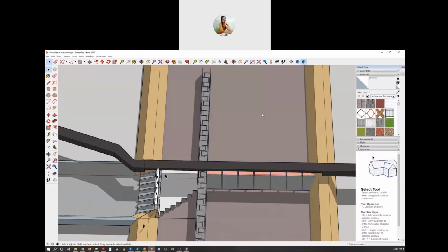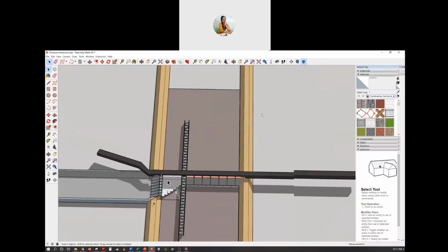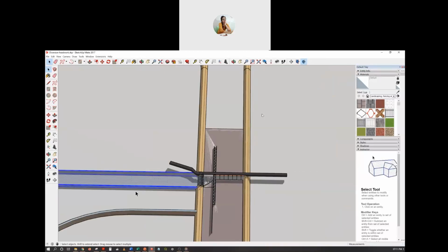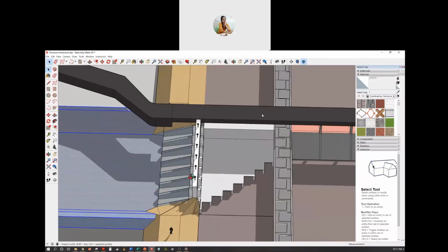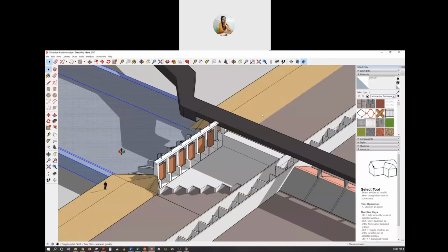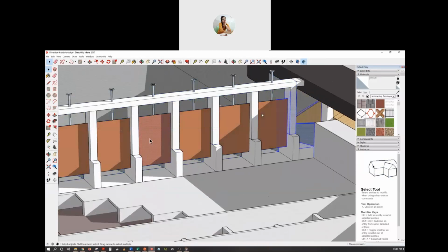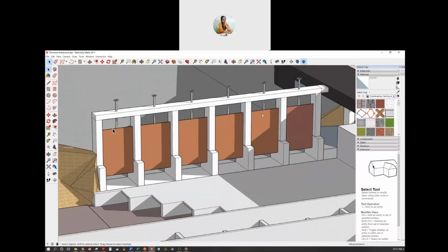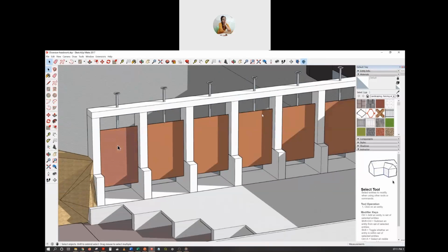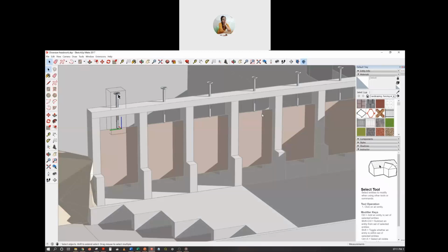Now, the off-taking canal is fed by these kind of work, which is called a head regulator. So a head regulator is provided with these kind of gates. So these are the gates. Mostly these are made of metal and they are raised or lowered based on need. So here I have only shown this kind of a steering or screw thread arrangement. If you rotate this, it will be either lowered or raised.